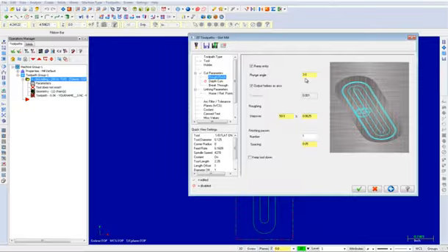A smaller plunge angle means that the entry move takes longer to descend in the Z-axis. A recommended angle is between 3 and 5 degrees. Output arc moves writes the entry helix to the NCI file as arcs. Using this option can create shorter NC files. If you turn off this option, the helix breaks into linear segments in the NCI file.